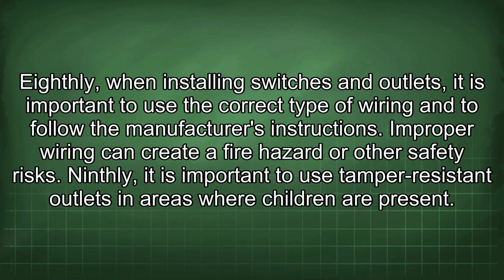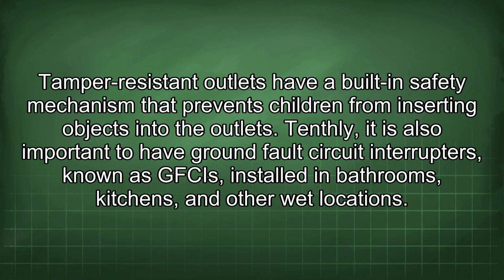Eighthly, when installing switches and outlets, it is important to use the correct type of wiring and to follow the manufacturer's instructions. Improper wiring can create a fire hazard or other safety risks. Ninthly, it is important to use tamper-resistant outlets in areas where children are present. Tamper-resistant outlets have a built-in safety mechanism that prevents children from inserting objects into the outlet.